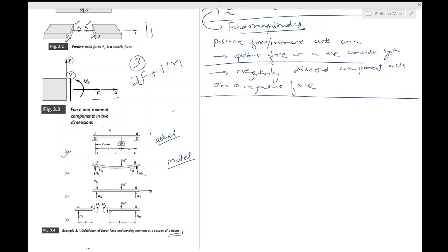This is the most general form with the normal and a frictional component. So the normal and frictional components of the forces will be acting at A and B. Now at this point we don't actually have much knowledge about the magnitude and sense of these friction forces. In the sense we don't really know what direction they will act and so on.